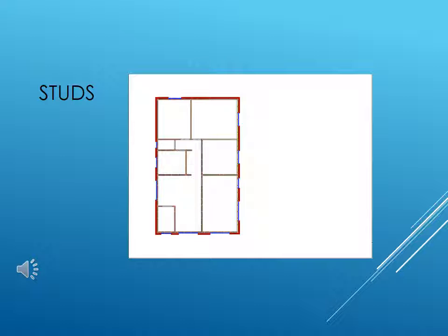Stud layout. Generally on a roof like we have here, which is a 4-hipper, the first stud that is set out on the job is the half span of the building structure. So in this case, that's around about 7.7 meters. Divide that by 2, and then you would actually move that along, and that would be your first stud. And the reason for that is that that stud sits underneath the first pair of common rafters.